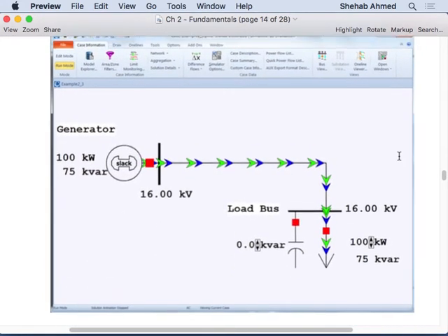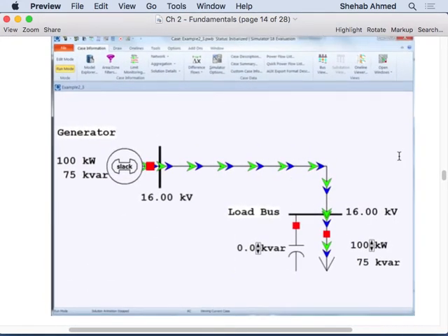And then you can also do this with PowerWorld. So you can confirm your answer yourself. You don't need to have a solution manual. You can simulate the system. So you have a generator here connected to a bus bar, connect a load here to another bus bar, connect them with a transmission line, and you can add a capacitor in parallel. And you can start playing with the amount of kilovars that you need to push real or reactive power. So I believe the green and the blue indicate here real and reactive power.